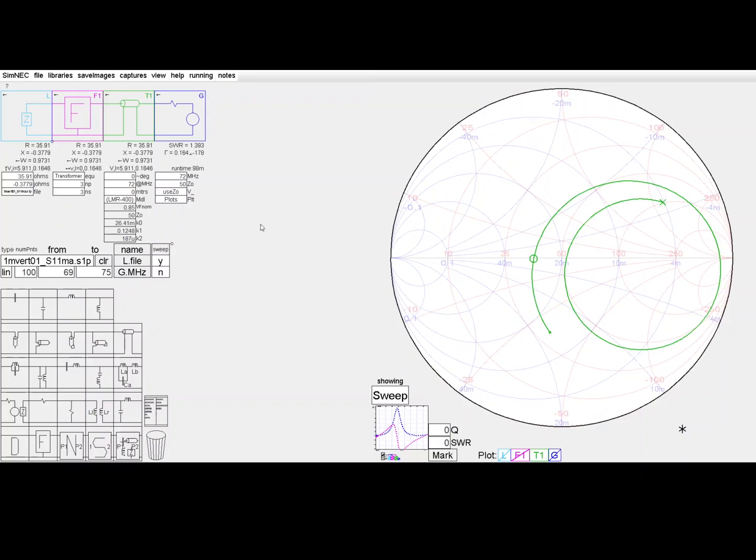So the thing that we've seen is that inserting transmission line, that is when you measure looking into a transmission line, the transmission line has the effect of rotating each point on the locus about the centre, but the rotation is frequency dependent because it depends upon the electrical length of the transmission line at the frequency where that measurement point was taken.